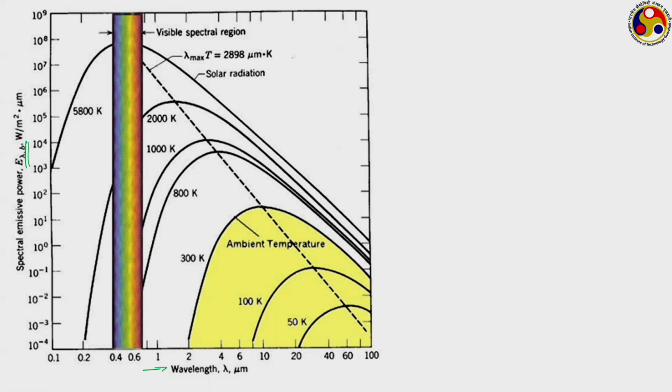Depending on the temperature of the source, you can see that each of them is taking some parabolic kind of shape. For lower temperature, the wavelength is also quite low, but as the temperature keeps on increasing, the corresponding wavelength increases, and beyond 1000 Kelvin the change is also quite significant, but for lower temperatures probably the change is much more dominant. And this particular relation is given by this, where on the left hand side we have the spectral hemispherical emissive power, which is given by a relation like this.